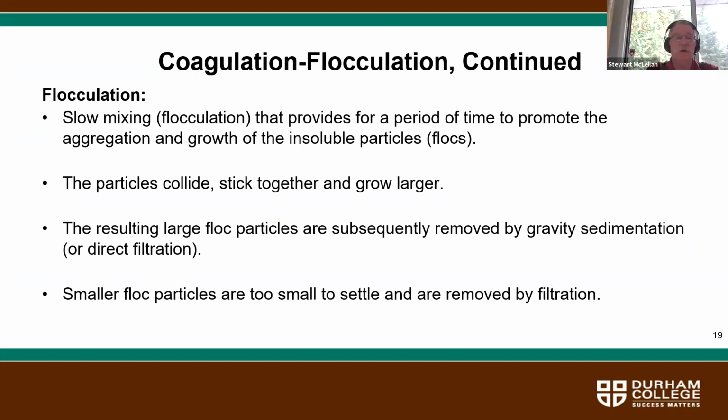These are just clarifiers that have inclined plates in them. As the water is pumped up against those inclined plates, the floc will impinge on the plates and will slide to the bottom of the clarifier.